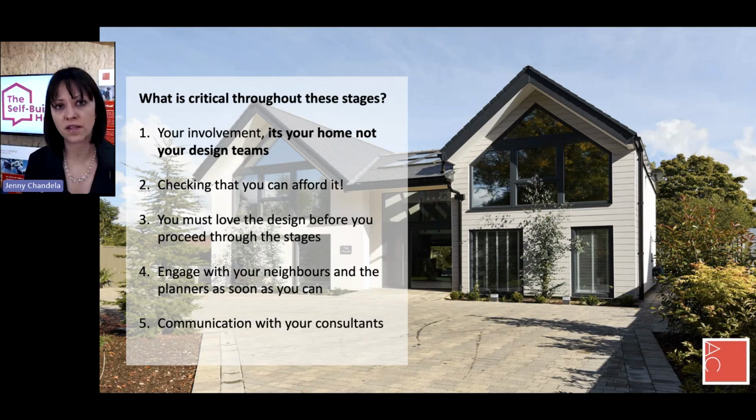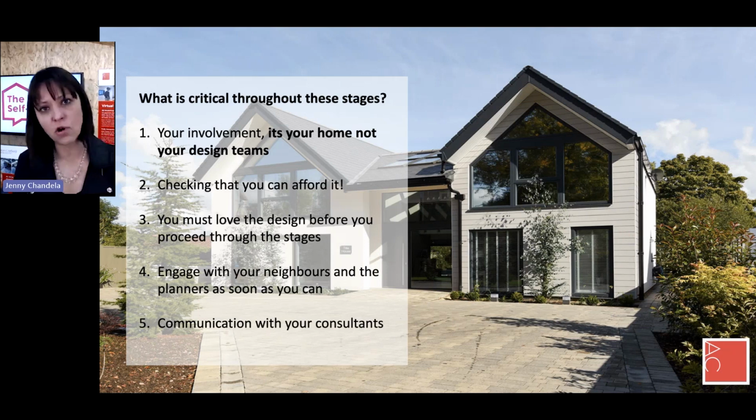So we'll be starting by considering the cost per square meter. And then as we get further along, we can start to get quotes for some of the big pieces, like the kit construction, the windows and doors, some of the systems that are going to go in. So you can start to refine that. And the further you go along, the better idea you'll have, pricing from different consultants or subcontractors that you're using. If you are using a QS, you can get this done at different stages. The further along the project, the more precise that pricing is going to be, and the closer, therefore, the smaller your contingency can get.